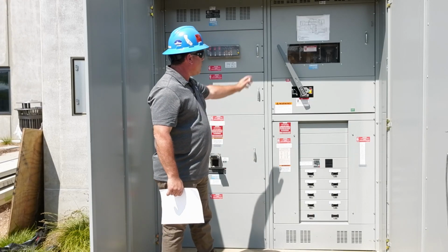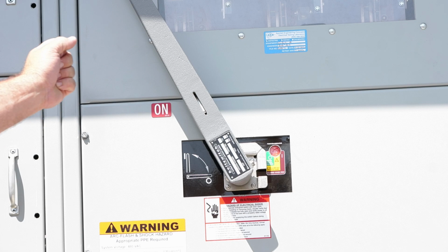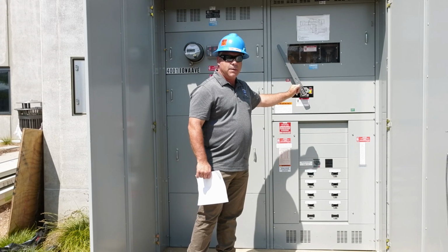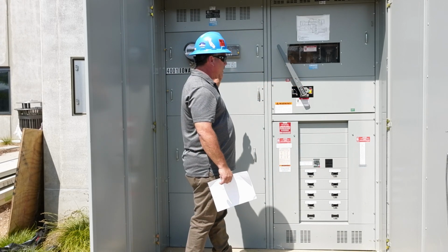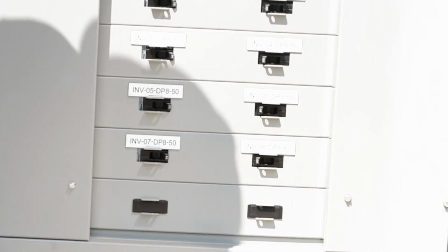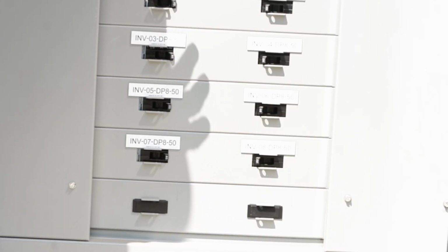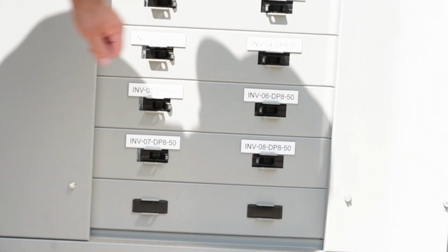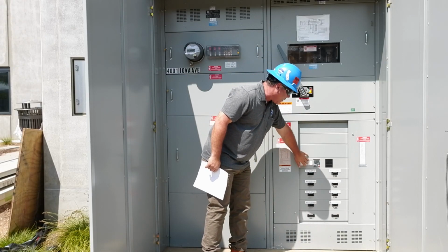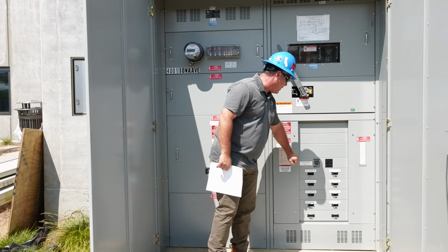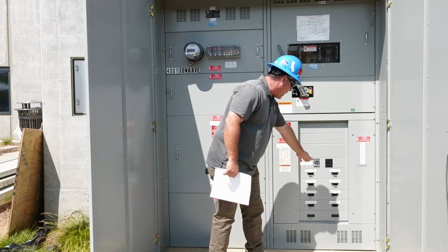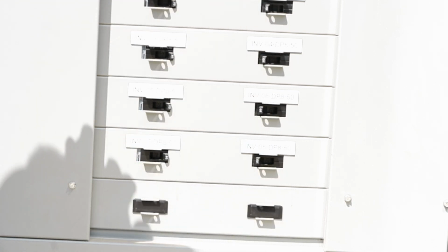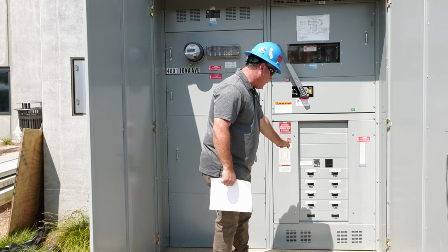From the main breaker, we go to our air switch on this section of the board. This section, same as the main breaker, if it goes in the open position, is going to disconnect utility from the distribution board. These breakers control every inverter that is being supplied from this distribution board. In this case, we have 1, 2, 3, 4, 8 distribution boards and an extra breaker that is controlling the meter cabinet. If we turn off any of these breakers, it will turn off the inverter, and we'll show that in a later part of the video.